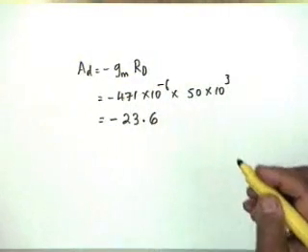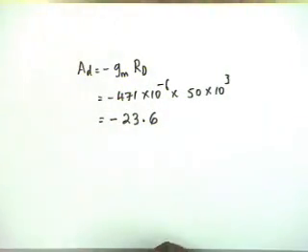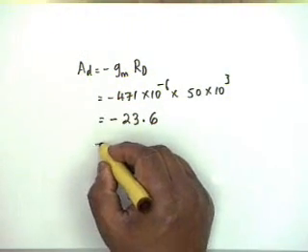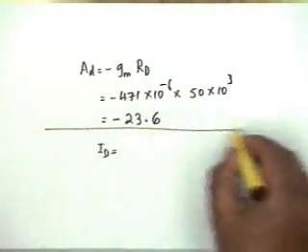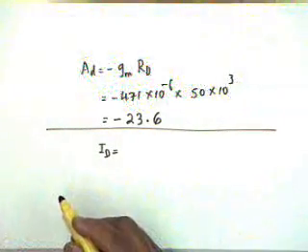Now, in order to calculate R sigma, it obviously has to be calculated from the application of a KVL. And that KVL we want to do through VGS. VDD, IDRD, VDSQ, and then VGS, then we go to ground.